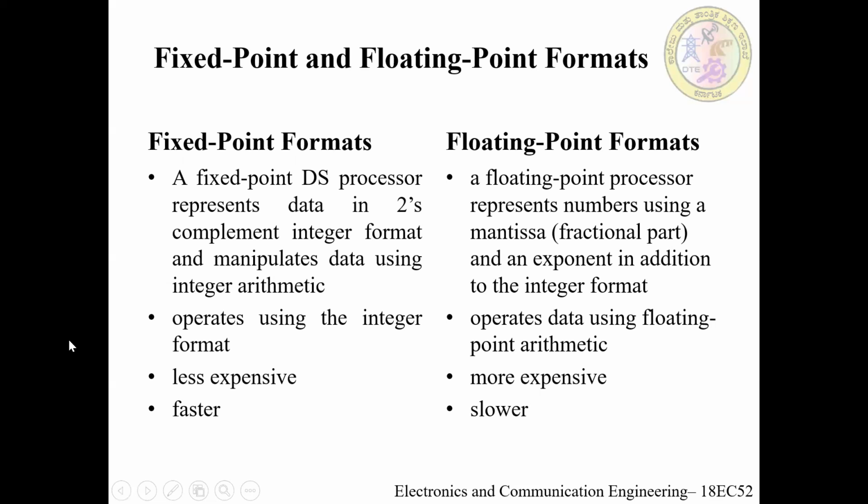As the fixed point digital signal processor operates using integer format, which represents only a very narrow dynamic range of the integer number, a problem like overflow of data manipulation may be possible. Hence, we need to spend much more coding effort to deal with such situations. We may use a floating point digital signal processor, which offers a wider dynamic range of data so that coding becomes much easier.